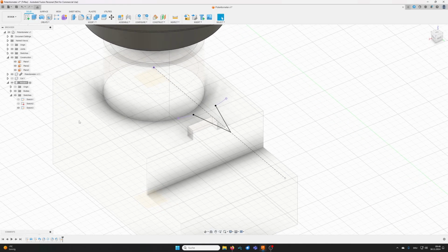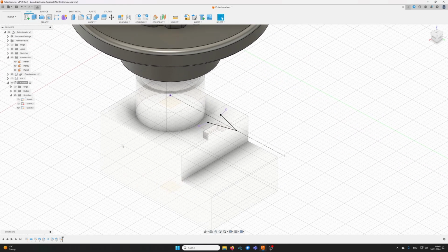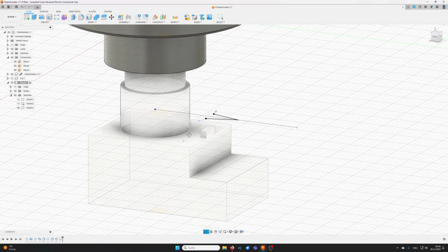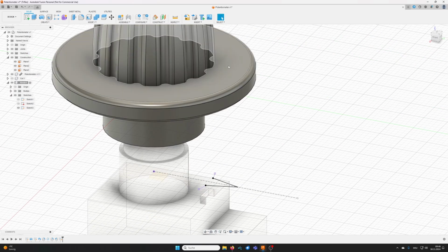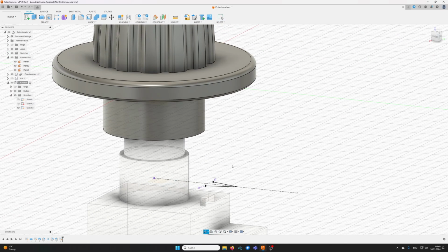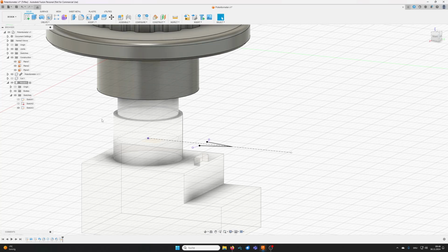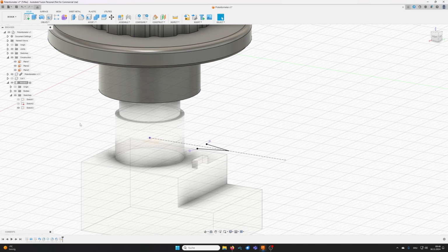Okay, but it's a nice opportunity to have a look at our sketch planes. I've selected the wrong plane for my sketch. I haven't selected this upper face. I selected another one. I'm not sure which one I selected, but it doesn't matter. I can either delete the sketch and create another one, or simply right click and redefine the sketch plane.